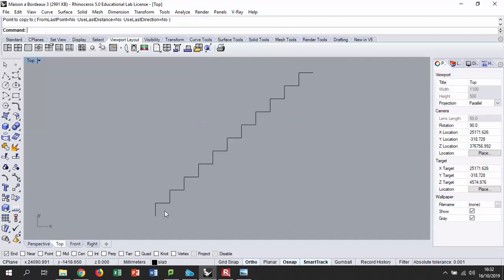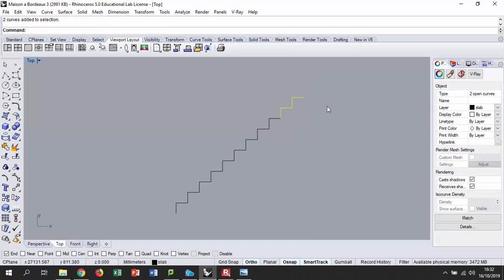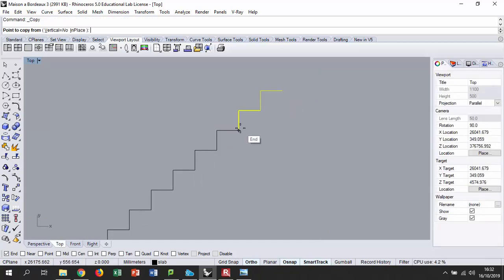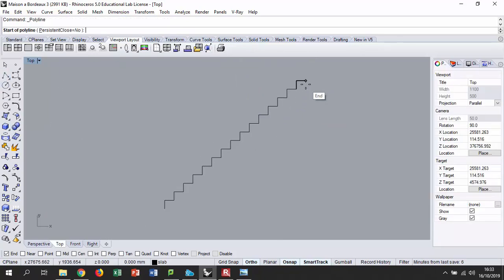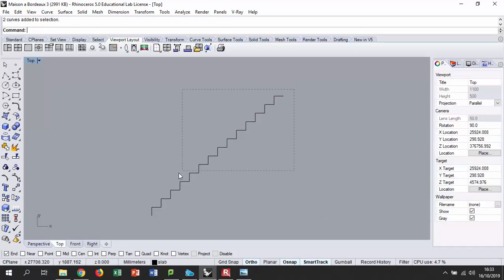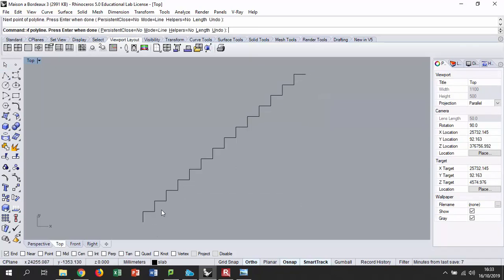So I have 13 steps overall, which should fit through that space that we've created before, which is 4.3 meter. I still have some steps missing. I think this is what we need. So one extra step. That's it. So this is my under element. The depth of the staircase is going to be around 20 centimeter.